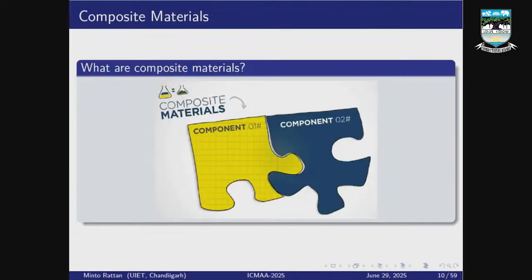The composites might contain aligned continuous, aligned discontinuous, or random fibers, particles, or whiskers of ceramic materials like silicon carbide, alumina, etc. in a matrix which may be a metal or an alloy. Because of their superior stiffness, high strength at elevated temperatures, and better creep characteristics, metal matrix composites are finding increasing applications in components exposed to elevated temperatures.